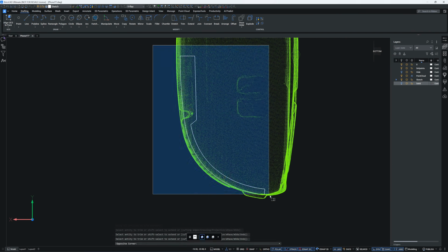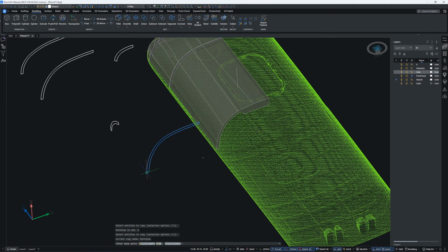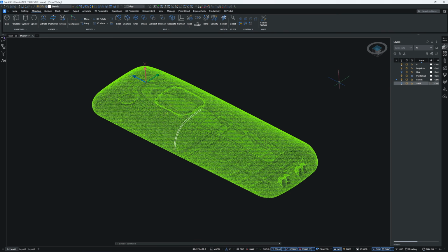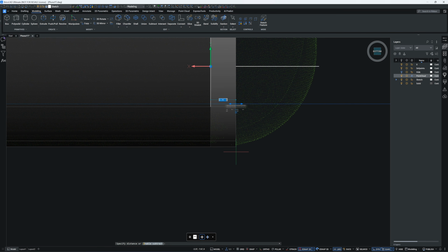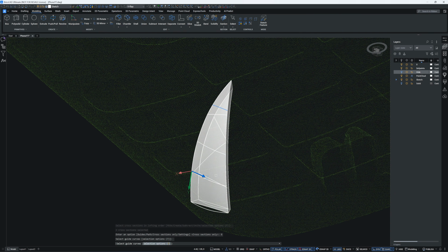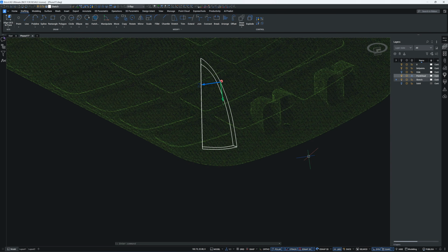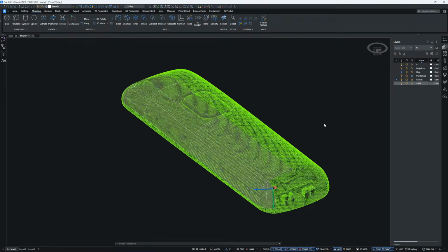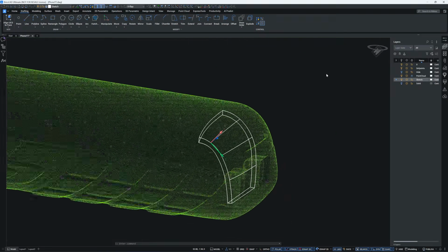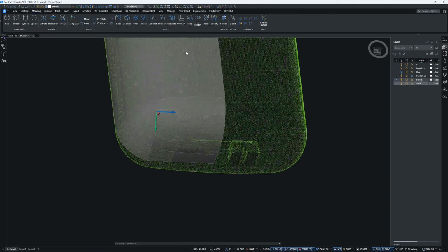I'm adding thickness to this section of the profile because I will imprint a rectangle over the top. This section doesn't change in profile shape along its length, so I will simply extrude it until it reaches the corner. I'm creating fan-out loft sections similar to the other end. One thing to note in BricsCAD, guide rails can only be lines, arcs or splines, not polylines. So when you extract an edge from the solid, you will need to convert the polylines into a spline first using the edit spline command.